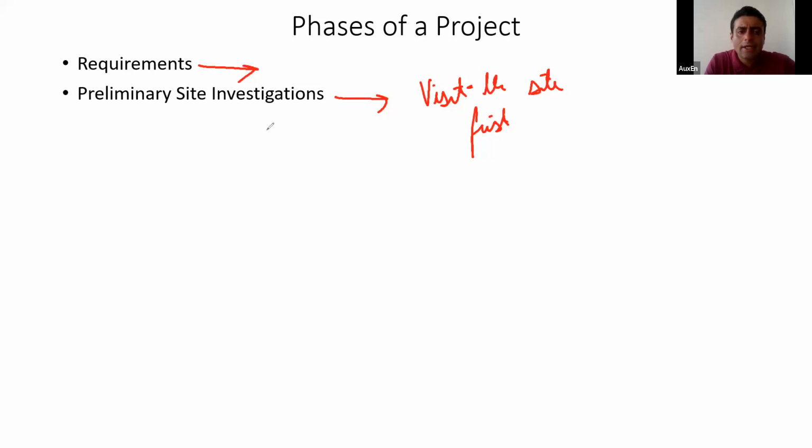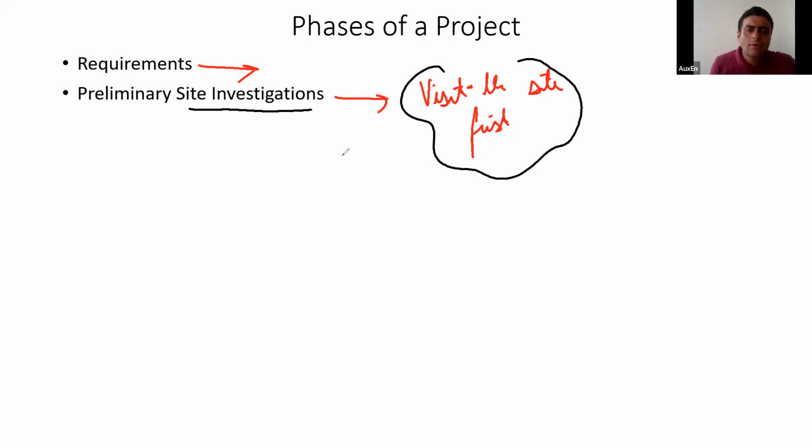That is a severe handicap that we face of not being able to visit the site. And if possible, I would say you should visit your site before starting any project. Not only visiting the site, but also carrying out some preliminary site investigations is very important.